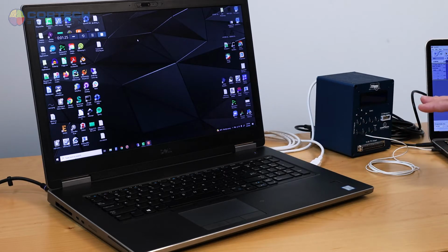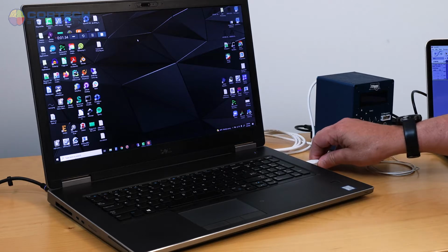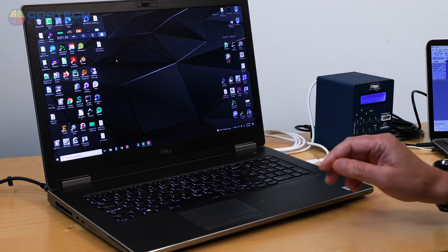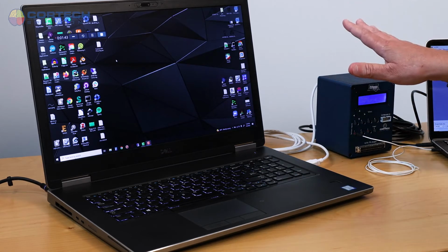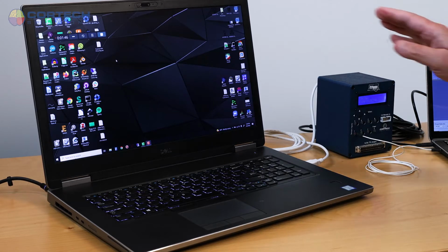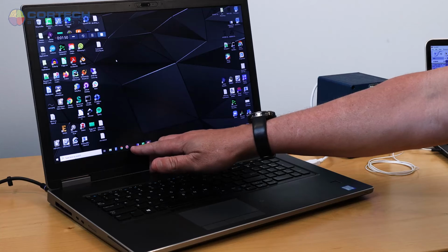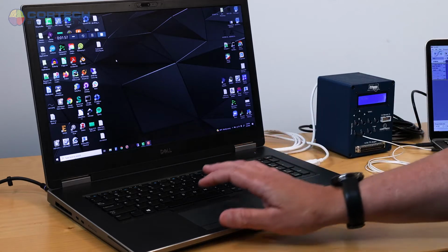Before I plug that in, I just want to show you a process that you need to go through in order to get the oscilloscope to be recognized. Once you plug it in, there's going to be a tone, and you assume that because this screen comes up, that everything is as it needs to be. But in fact, for the oscilloscope software, TracerDAQ, this little icon, to be able to recognize the oscilloscope, it needs to be in a short list of recognized devices.